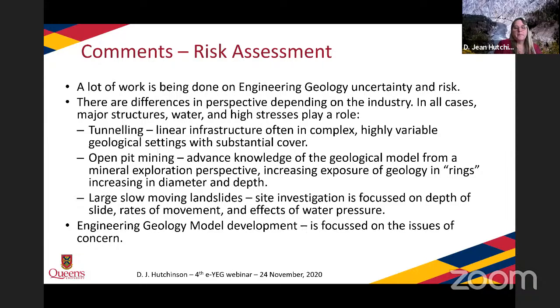In open pit mining, there's some advanced knowledge of the geological model from a mineral exploration perspective, from all the drilling that's done to prove out the ore body. And there's an increasing exposure of geology in rings as the pit progresses, both in diameter and in depth. As you get those more substantial depths, you get into circumstances where you can move from relatively small scale failures at the bench level to larger, deeper seated pit wall failures. So again, quite a different way of thinking about risk because of the way you're exposing the material and what you know about it.